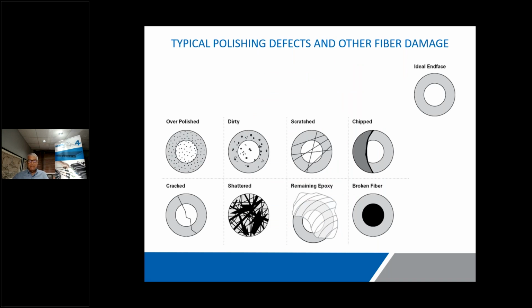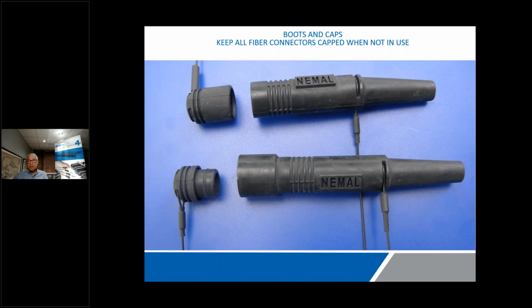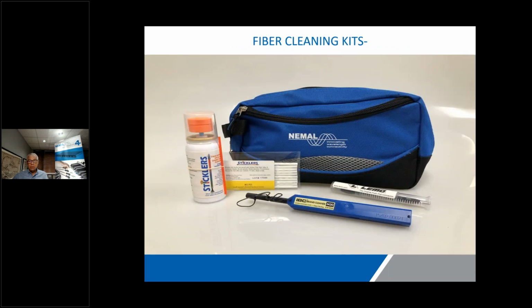So you can see these are some of the standard things. I have to emphasize that the biggest three issues we find are dirt, dirt, and dirt. So please keep your connectors clean. We recommend that you clean a connector every single time you connect or disconnect it, as well as keeping it covered with a boot or other similar protection whenever it's not in use.